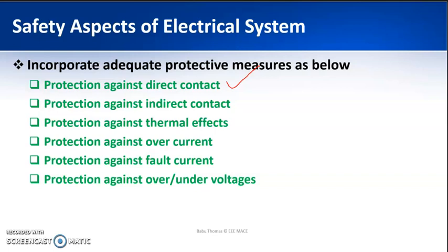So even if you get in contact with that body, to which some electric current passes, since the body is already earthed, you are protected. You have to prevent the fault current from passing through the body of any person or livestock, or limit the magnitude of the fault current, or use automatic disconnection of the supply, to protect a person from indirect contacts.